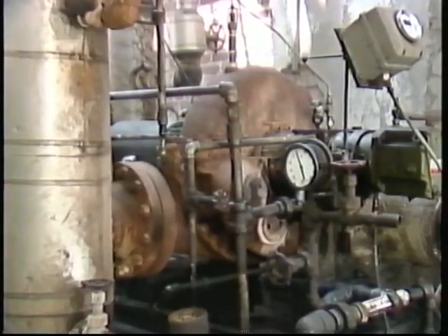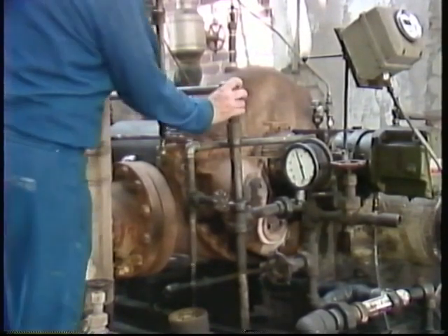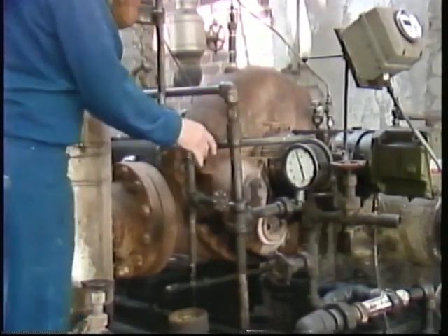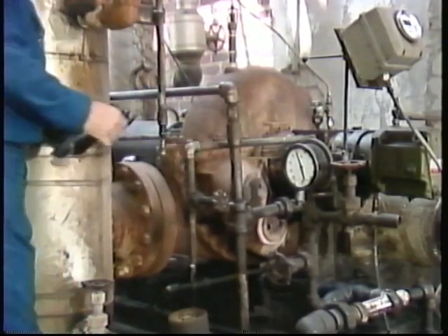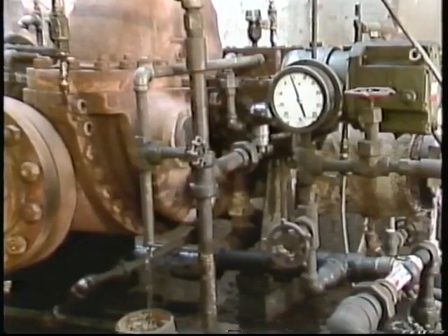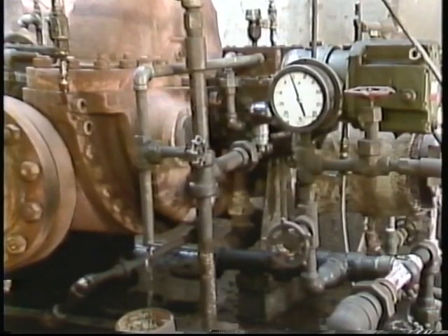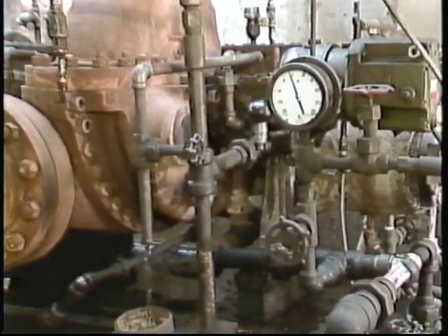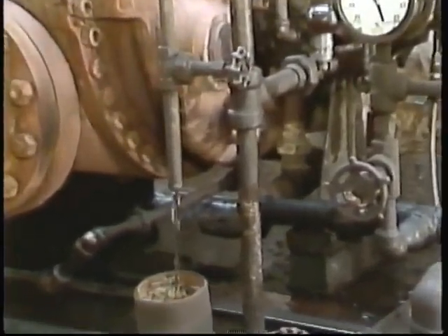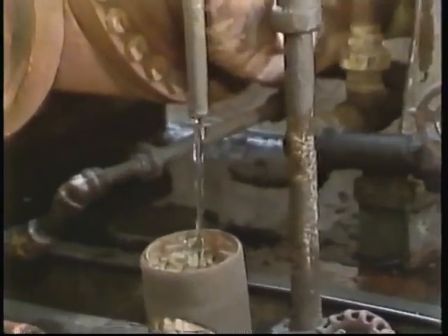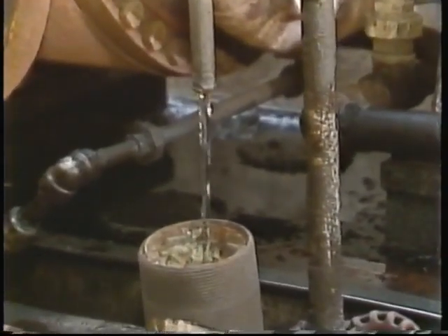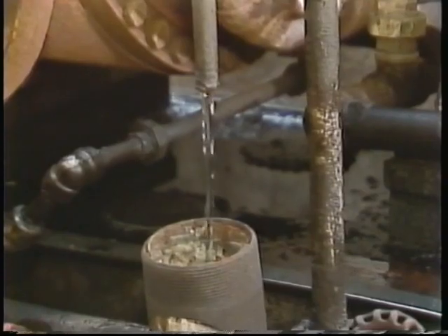One way to determine if this type of cooling system is functioning properly is to feel the cooling water lines and check the water being discharged after it has been circulated through the bearing jackets. If the water lines feel cool and water is discharging, the system is probably functioning properly.